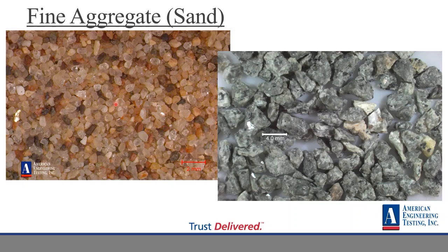In Minnesota here, the difference is we have so much sand that typically in our sand and gravel pits, we get about 30% gravel, which means any rock typically retained above the number 4 sieve, or 4.75 millimeters or higher. So that's coarse aggregate, you would call it. And we get about 30% of that in a good sand and gravel pit. So that means 70% of that is sand.